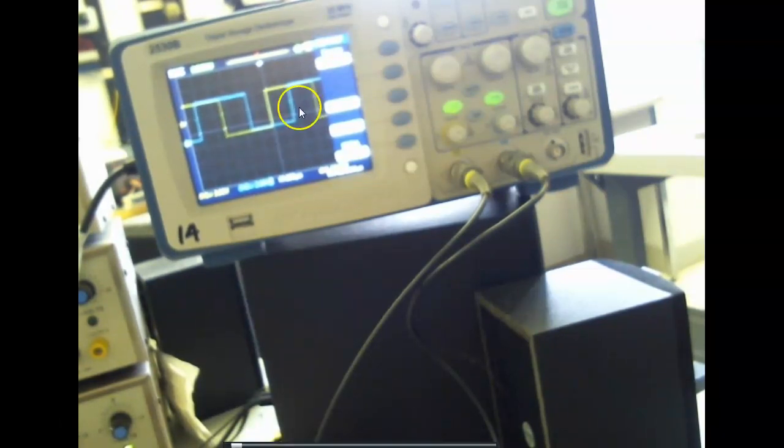And what we could do, and this is what they were saying, is count both. If my counters could count both of them, then that would be 32, right? If we had counters that could count both the rising and falling edges of both signals, then we'd have 64. But normally counters don't do that for us. Are we okay? This makes sense. Okay, so how fast is my motor going?